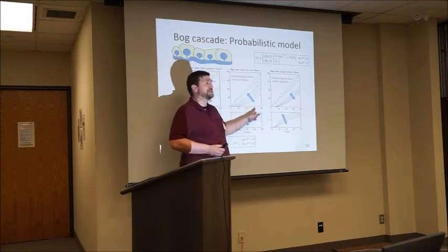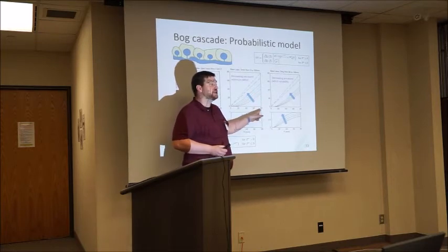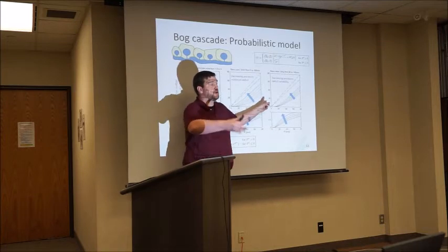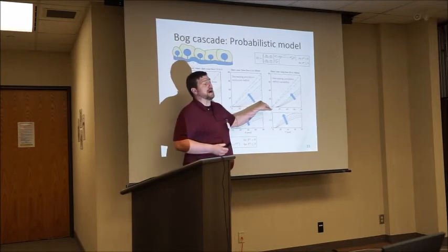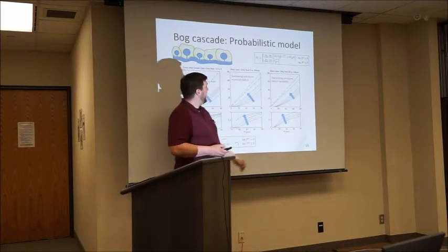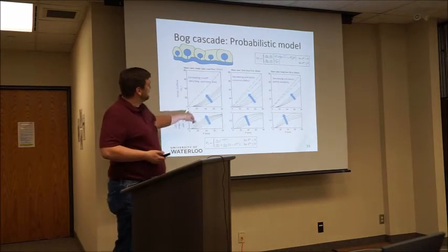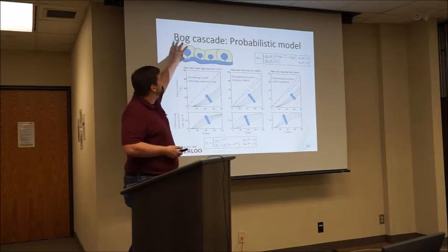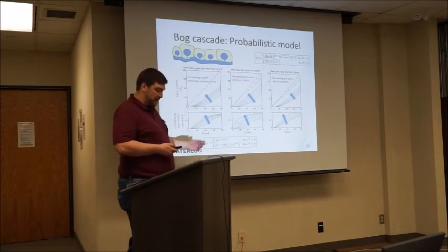And then as the precipitation event increases in magnitude, more and more of those bogs are filling up and then cascading and overflowing, leading to more outflow from the basin. And so that's for a one bog system. Similarly, this is going to change with the distribution of the contributing areas for each one of those bogs. We can solve that analytically.